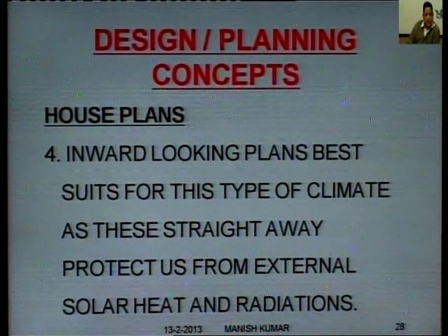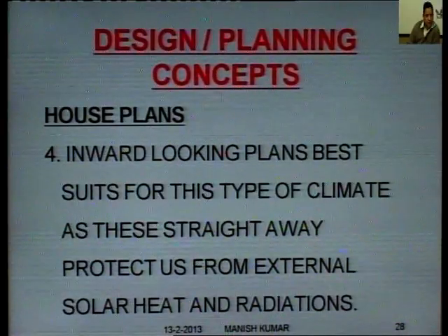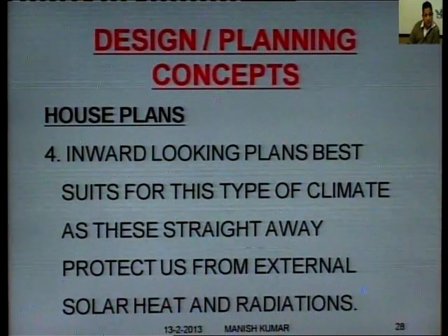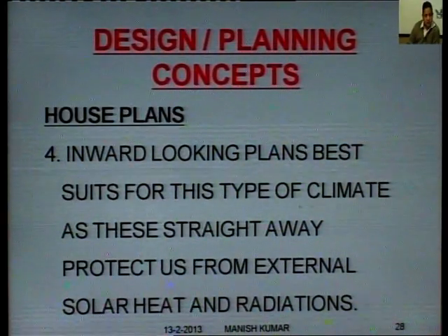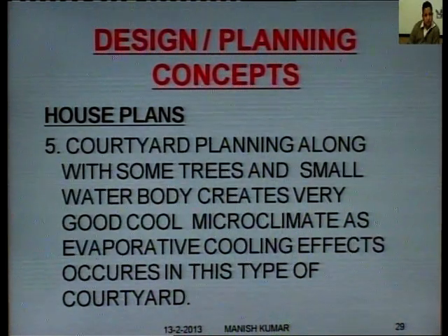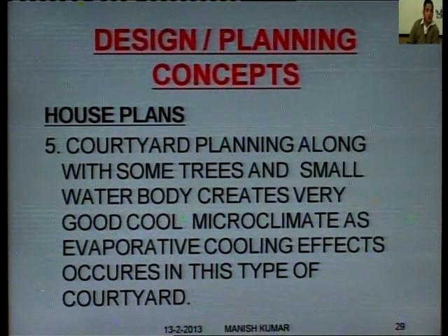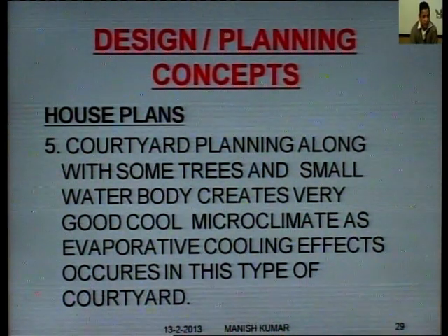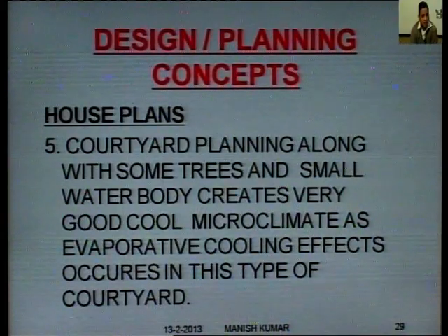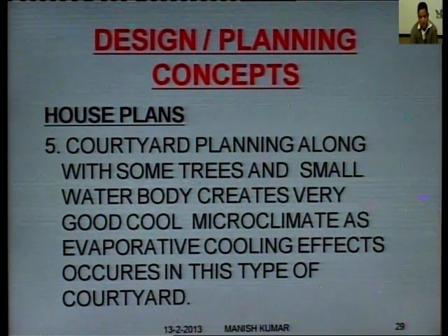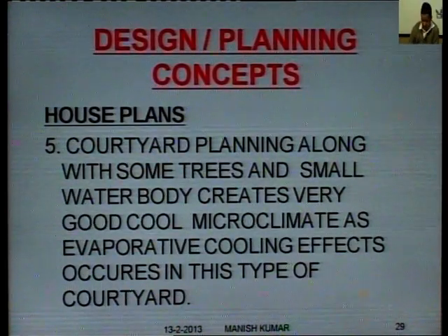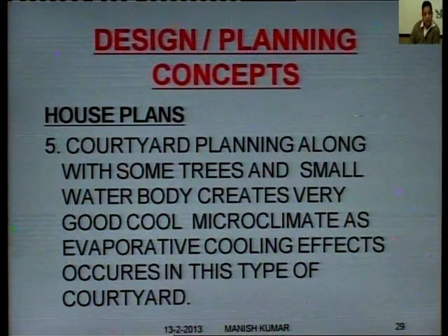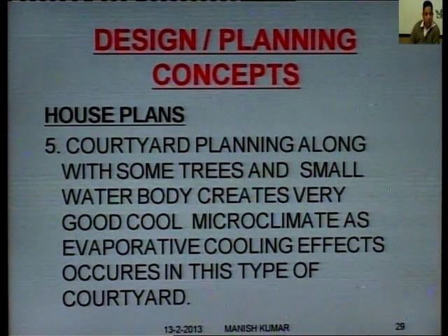The next point is that inward looking plans are best suited for this type of climate, as these straight away protect from external solar heat and radiation. Yes, introvert planning is good. Next, courtyard planning along with some trees and a small water body creates a very good cool microclimate, as evaporative cooling effects occur in such courtyards. Yes, courtyard planning best suits this type of climate. Courtyards create a microclimate which cools all the parts of the building surrounding the courtyard.